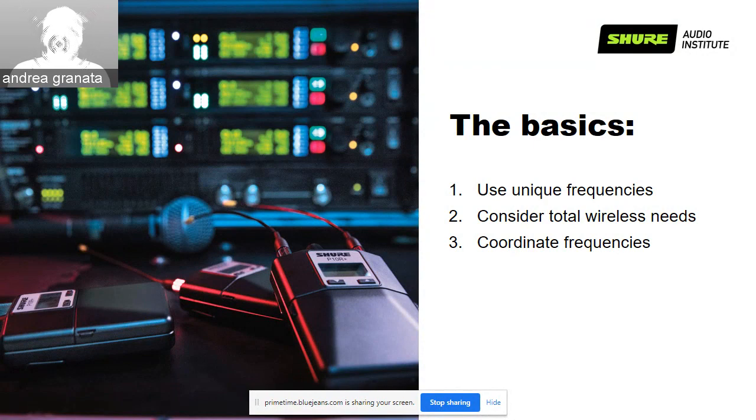As we discussed in one of the first episodes, we need to remember that we are using the RF spectrum on a secondary user basis, meaning that we can use whatever is available as long as we don't create interference to primary users. Most of the time, in a great part of the world, the primary user is the TV band. Primary users are TV broadcasters. They broadcast at much higher power than we do, so it's extremely unlikely that we can create interference to them.